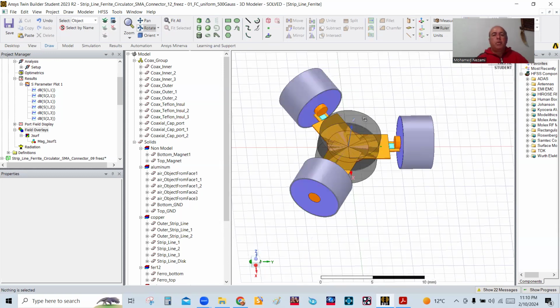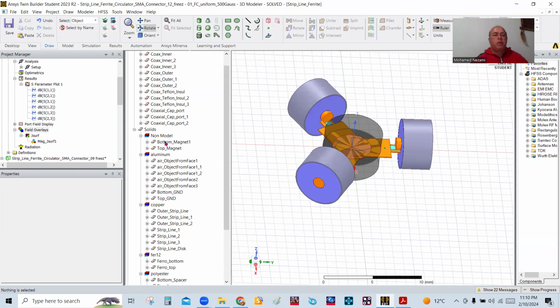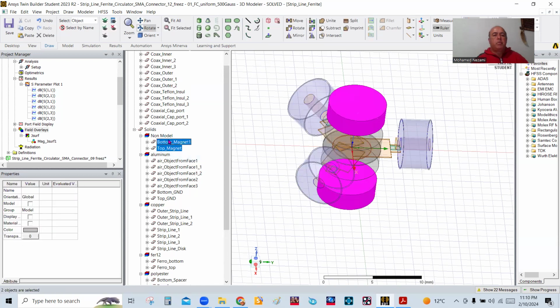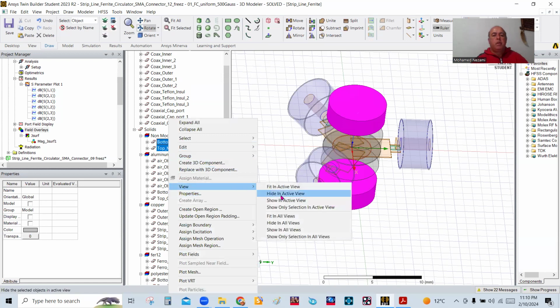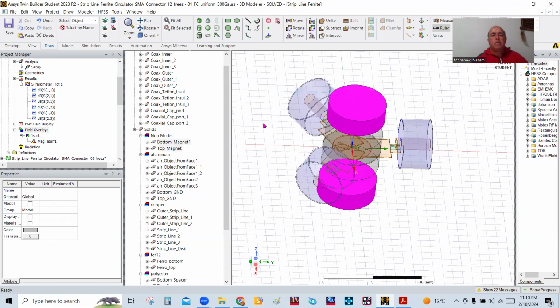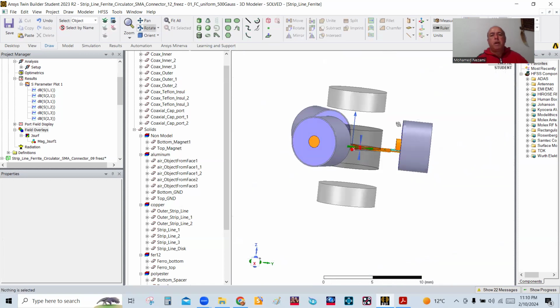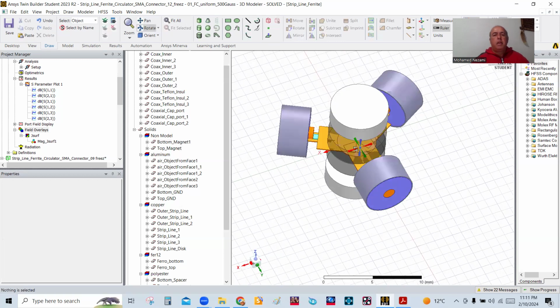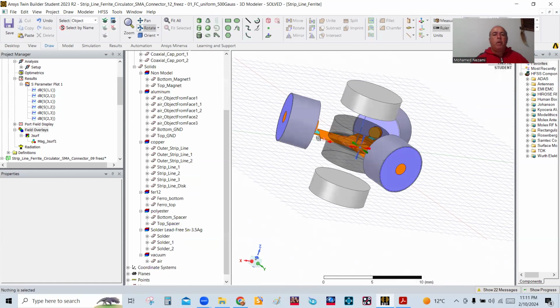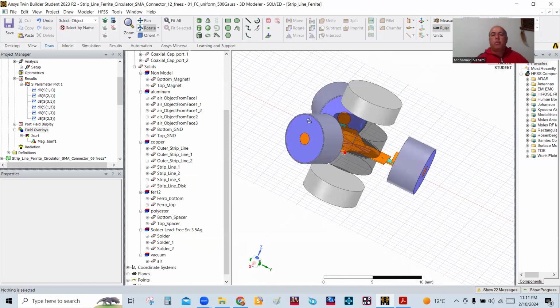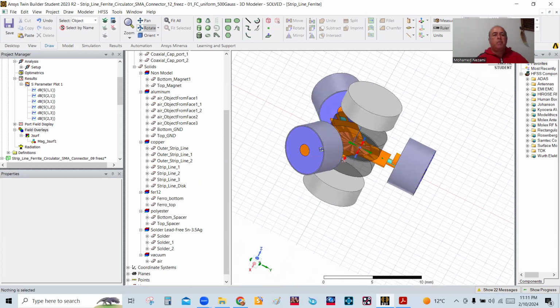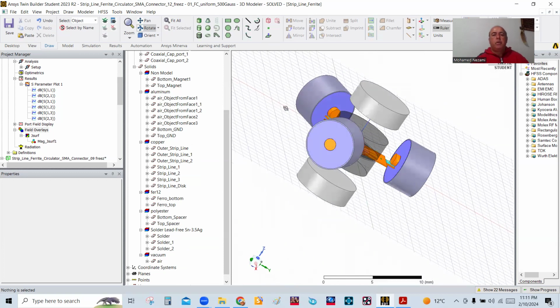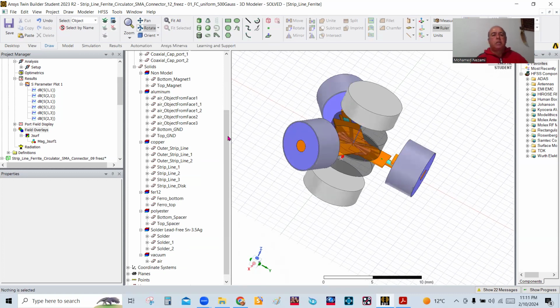All right, so now let's put the rest of it. Let's put the magnets, show the magnets in there physically, okay? So basically, here are the magnets on top of the ferrites. And then let's see what else. Oh, now to excite the coaxial waveguide, transmission line, you have to put it on the face in here so that it's a TEM mode. And in order to do that, you have to create a disk in here as well.